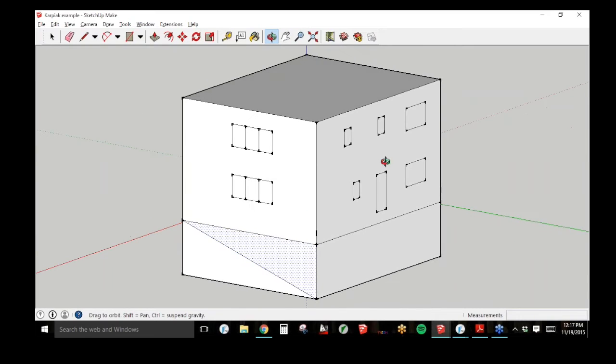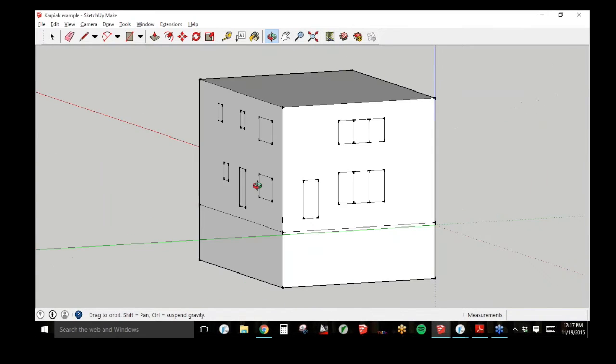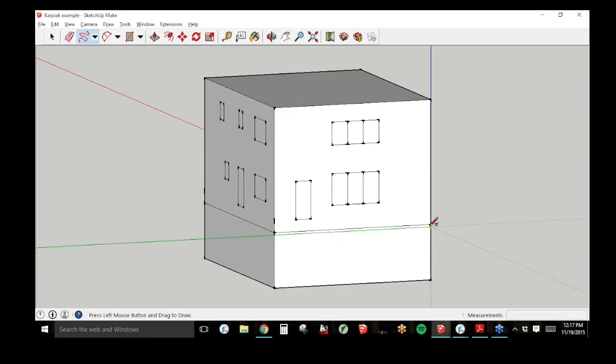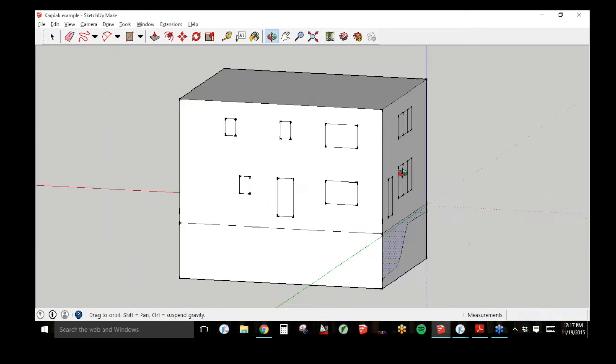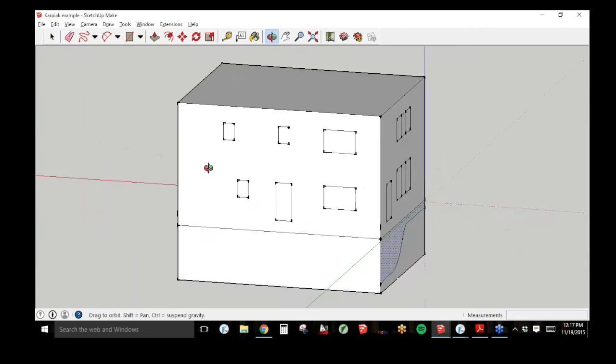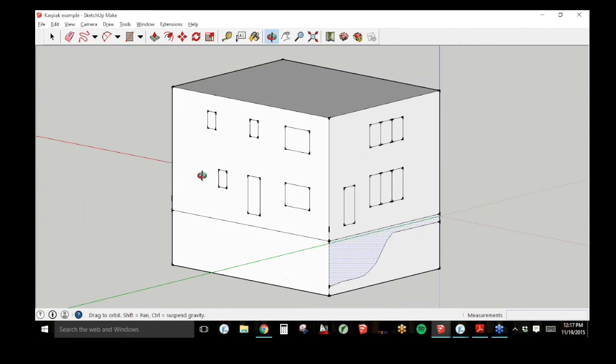Or, let's say on the other side over here, if you know the grade line, or you know it's going to be a pretty dramatic drop or something, just draw on the real line and then draw whatever the grade is. And now you've drawn two different clickable components here. This is important when we get into the next step here, which is assigning the boundary conditions on each side.